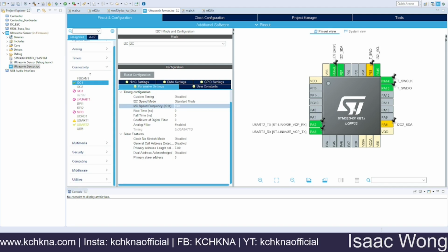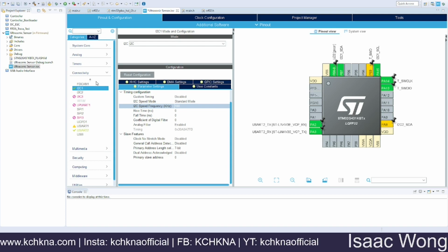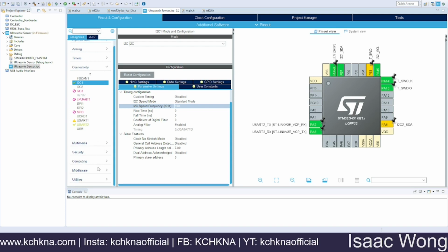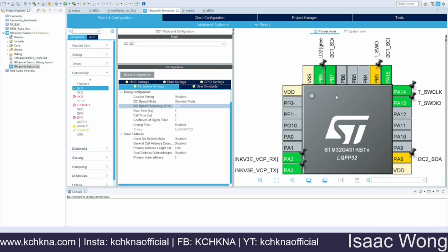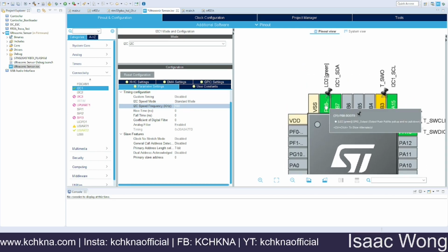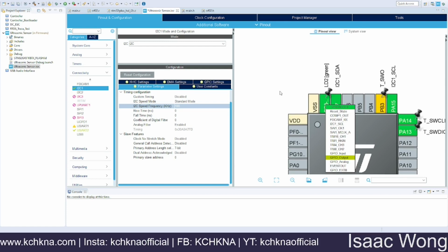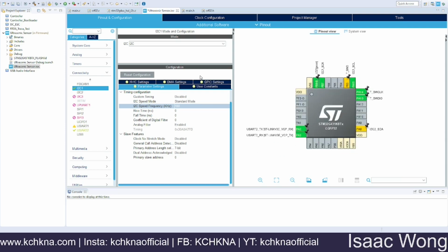So that's about it. Then for I/O pins, previously we looked at the register directly, turning it on from there, but we actually don't have to. To actually turn on the I/O pin, I have configured this. It's pre-configured as LD2, so you can see here it says GPIO output. Now I've already pre-generated the code, so I don't have to generate it, but when you save, it will ask you whether you want to generate the code.